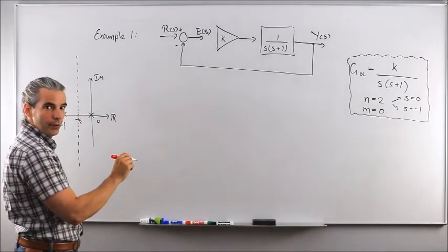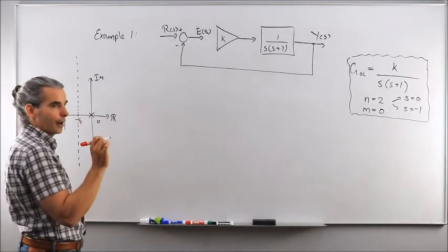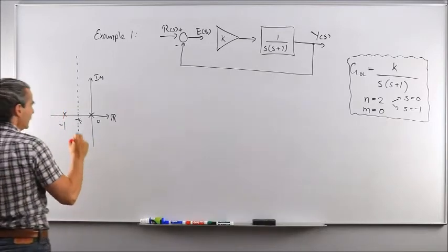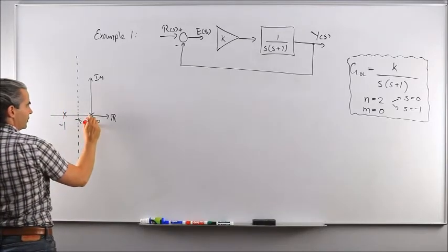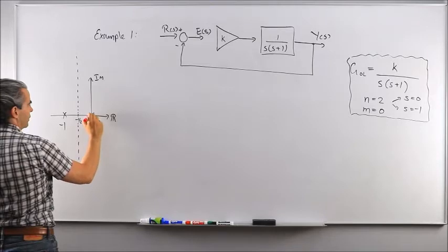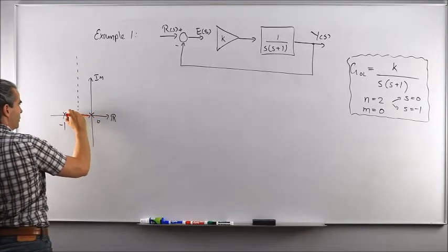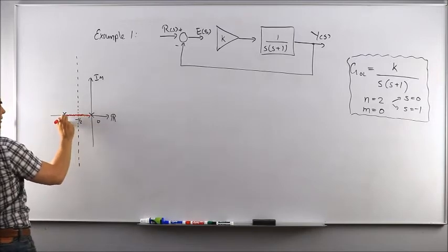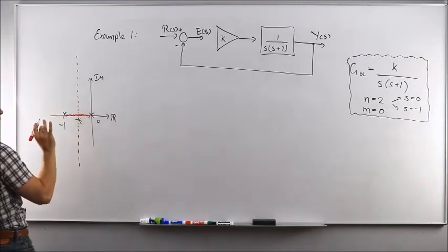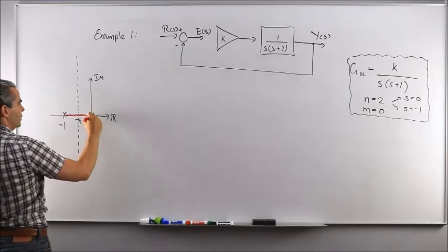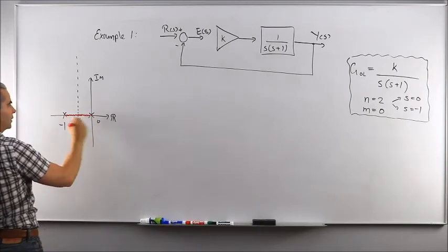And if the number becomes an even number, pen up and you stop drawing, okay? I'm starting at the origin. There's already something there, so that's 1. 1 is odd, pen down. Oh, the second object, pen goes up, and I stop drawing there. Meaning that the root locus will be comprised on the real axis between those two poles.